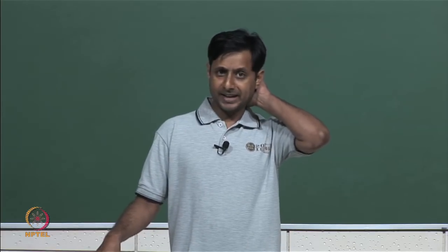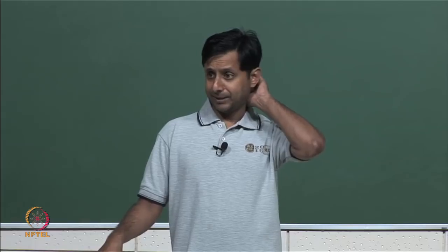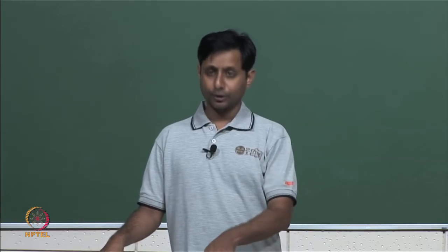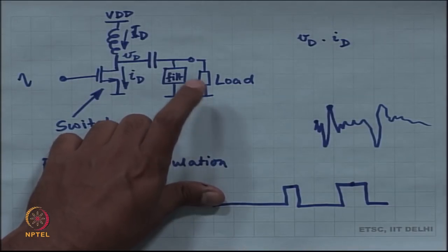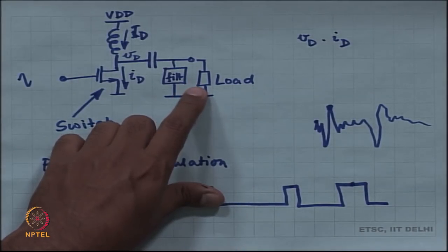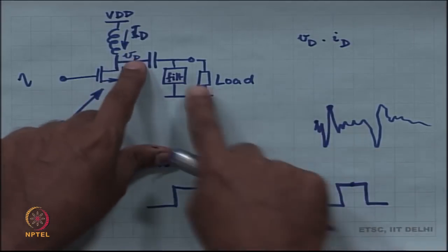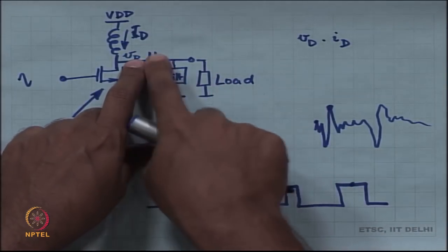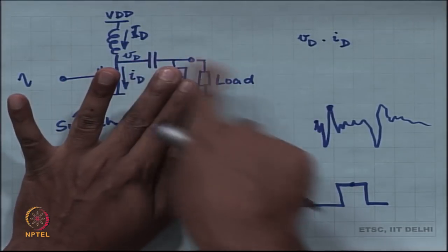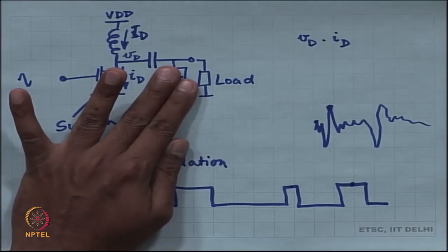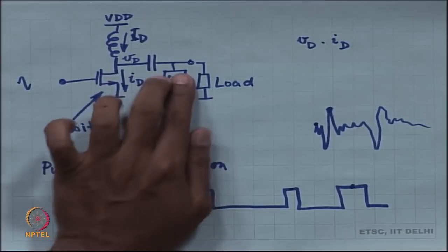In a lot of other applications, they say that the load is inductive. In an audio speaker, the loudspeaker itself is an inductor. So, you form an LC filter over here right away, and you engineer the LC values such that you get the right filtering. This is also something that a lot of engineers do. So, they eliminate this separate filter altogether.